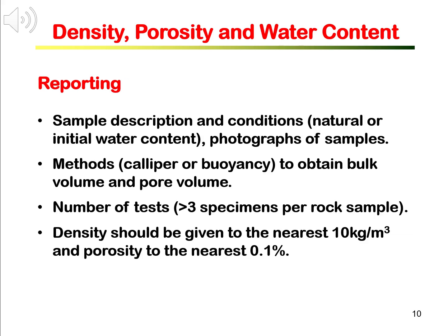Test report should include descriptions of the sample, rock type, location, how sample is collected and stored, the initial or natural water content. Color photos of the specimen should be attached. It should also include how the specimen volume is determined.